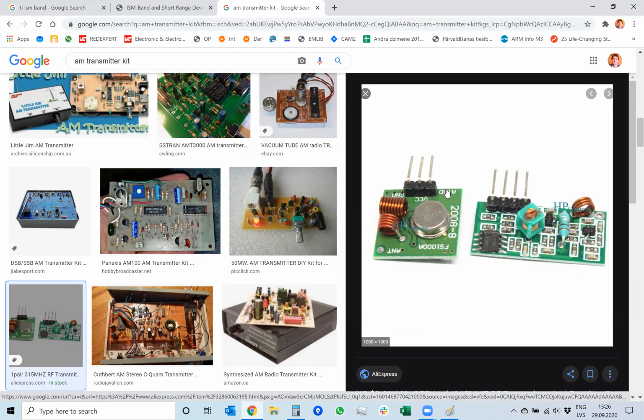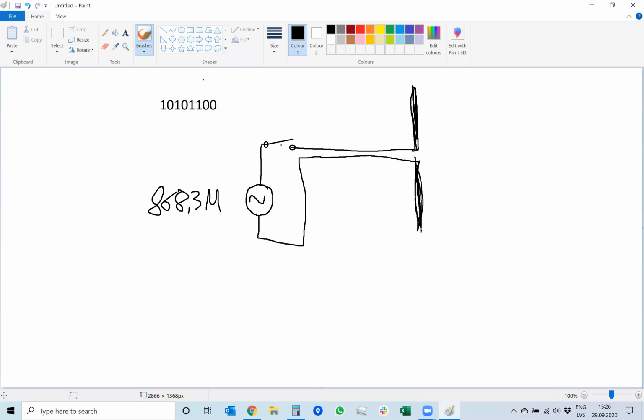You connect it to an antenna, and if you give it power supply, it will turn on and transmit. And if you disconnect the power supply, it stops transmitting. So this way you could make a very primitive amplitude shift modulator. And this is done in the car remotes, actually. Very, very simple schematic. This is why car remotes should actually be pretty cheap. They aren't because they're exclusive, but you know.